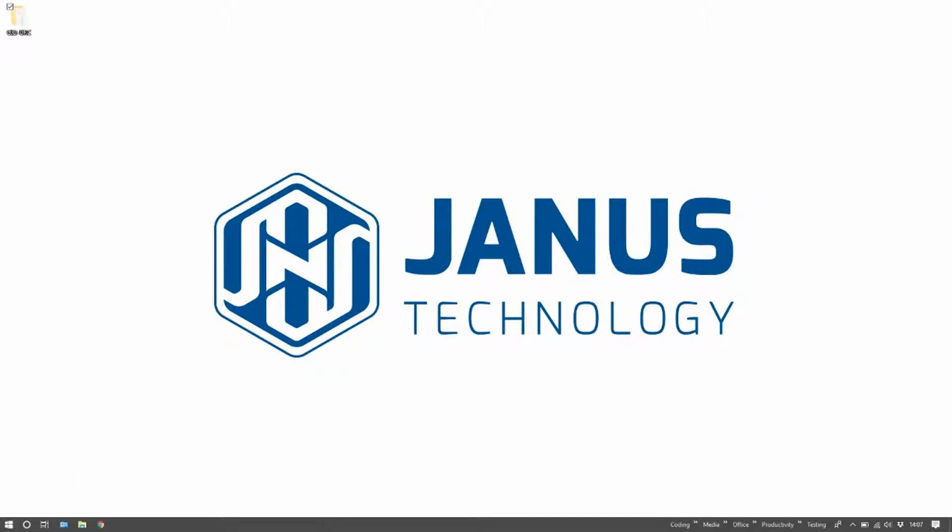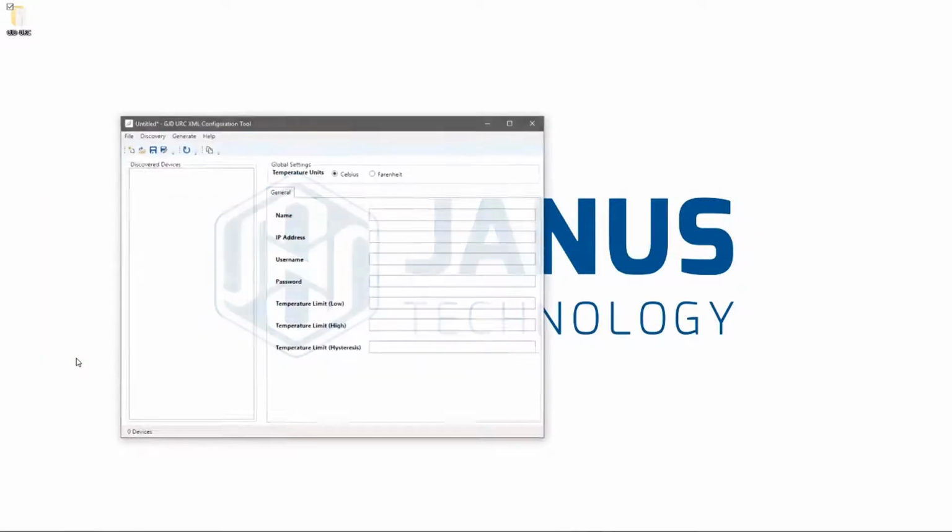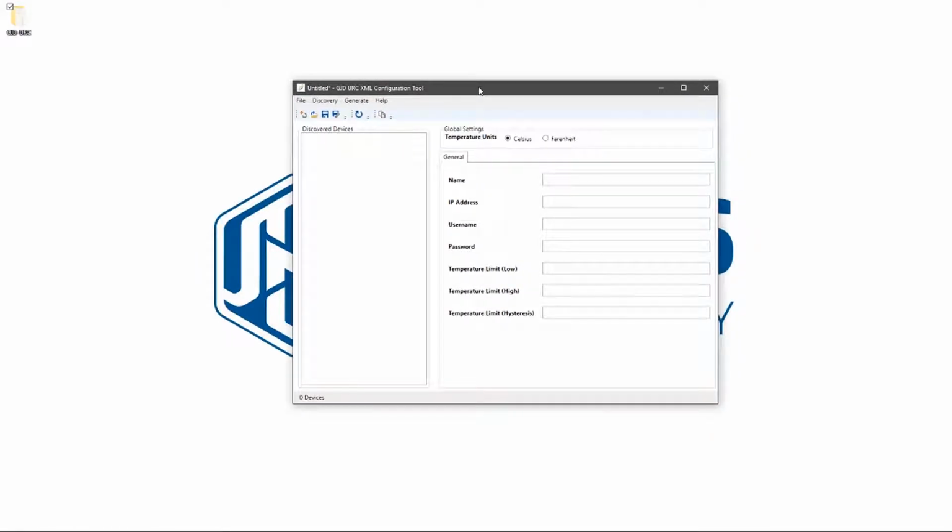So now that's installed, we can go down to the Start menu, to the GJD folder, and open up the configuration tool. The first step that we need to take is to discover devices. We can use the shortcut here or go up to Discovery. It'll take about 10 seconds to complete whilst the progress bar in the bottom right hand corner does its thing. And we have our three devices here: the Detect, the IP Anything, and the Clarius IP Illuminator. So what we'll do is click each one in turn, and we will give the user credentials for each device.